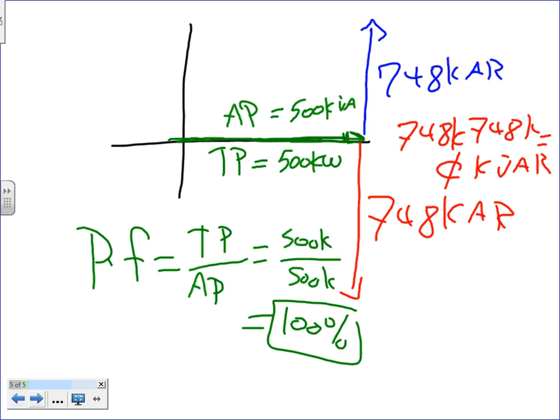They have synchronous motors, and believe it or not, they have a rotating, unloaded motor. Spencer, you have a big fat motor sitting there. The rotor is sitting here, and there's nothing attached to the rotor. No fan, no pump, nothing. So it's just sitting there, unloaded and spinning. If you guys remember, the induction motor has no wires coming out of the rotor, right? But the synchronous motor has a coil inside the rotor, and they bring DC voltage to excite it. They call it exciting the synchronous motor.